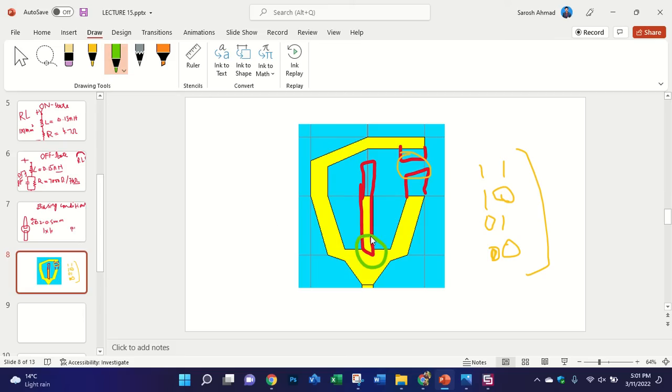Okay, at this position I can create a slot, and I can put my diode here. Maybe because of this strip line it will give me another frequency band. So you can check. Also, you see there are three resonators inside, three poles inside. The first pole is this one, the second pole is this one, and the third pole is this one. Maybe this antenna gives me a tri band antenna.